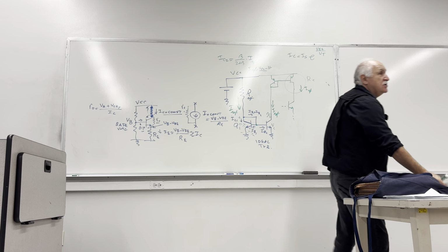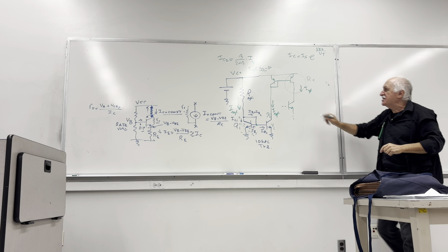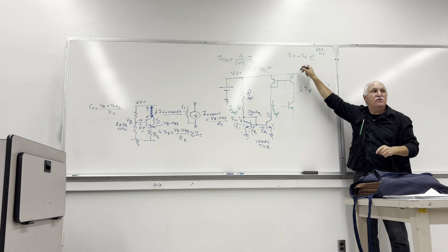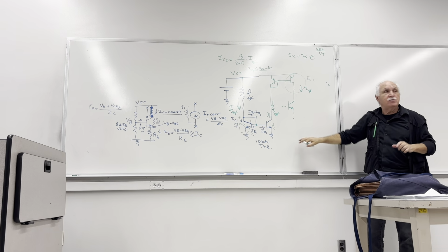So remember, in the common emitter amplifier, we used to have a gain of 100, because the RC was 1K, 2K, 3K. What if your RC is 100K? 50 times more. Then your gain of 100 or 180 will be 50 times 100 or 180. It will be 10,000 out of one common emitter amplifier. So this is known as active collector load with a large dynamic resistance. It will be able to bias it.